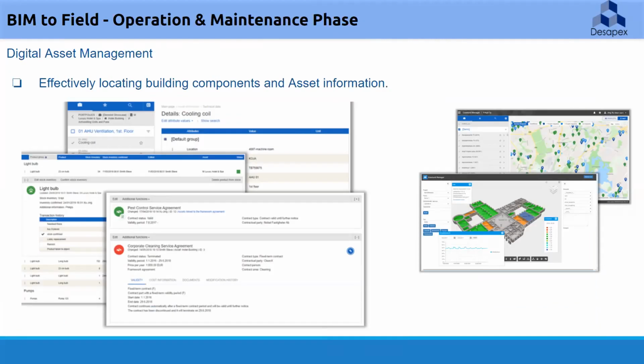The last and longest phase of any project is operations and maintenance. Simplifying this process will support owners in easy maintenance of the building. Having all the data in one format reduces the duplication of data and confusion. All the teams can refer to one single format of data, which will reduce a lot of confusion. By asset labeling the components in the BIM model, we can effectively locate the equipment at the site, and all the data fed into the element can be extracted for operation and maintenance of the equipment. It reduces the time required for extracting right and accurate FM information, which will help to respond faster at the time of maintenance or breakdown.